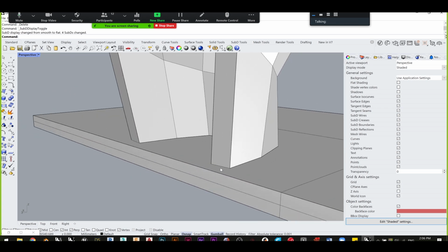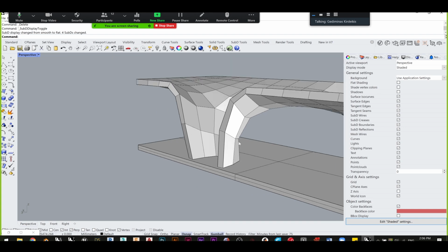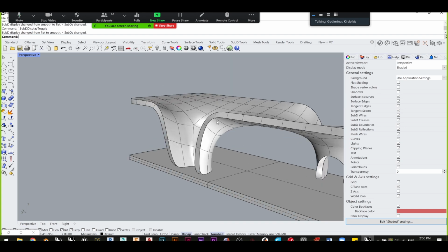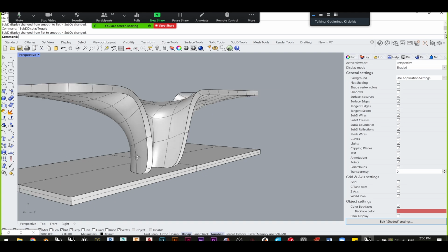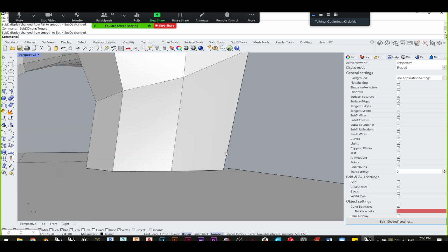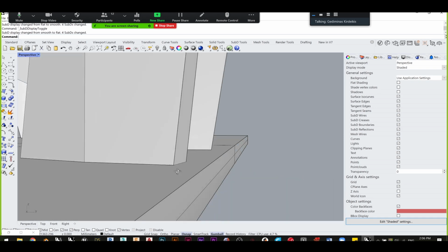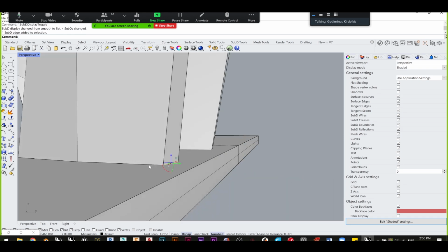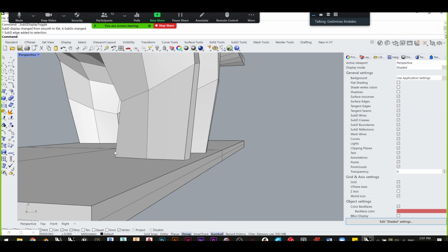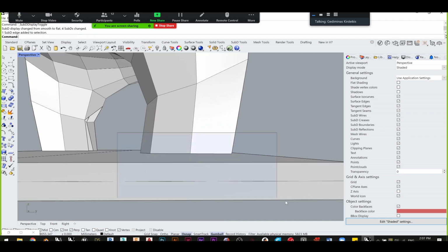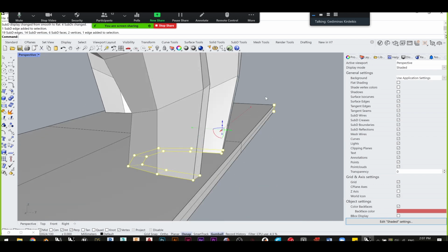What else? You can lock the perimeters in place and you can make it even more sharp if you want to, right? Because here I have this filleting. You can sharpen out the fillet by introducing a crease to the bottom perimeter, but I don't think that's necessary.